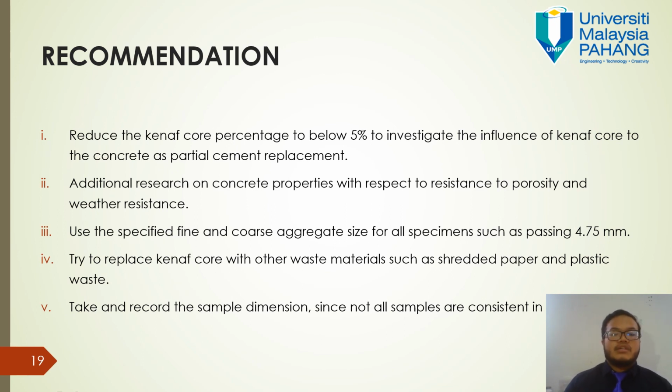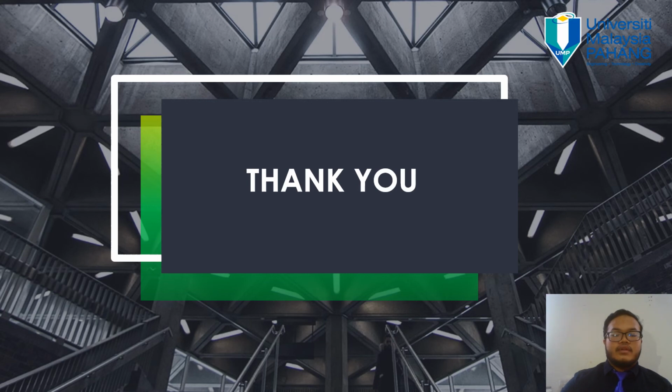Number 2 is additional research on concrete properties with respect to resistance to porosity and weather resistance. Use a specific fine and coarse aggregate size for all specimens, such as 4.75 mm or below. Next is to try to replace Kenaf core with other waste materials such as shredded paper and plastic waste. And lastly, take and record the sample dimensions since not all samples are consistent in size. So that's all from me.